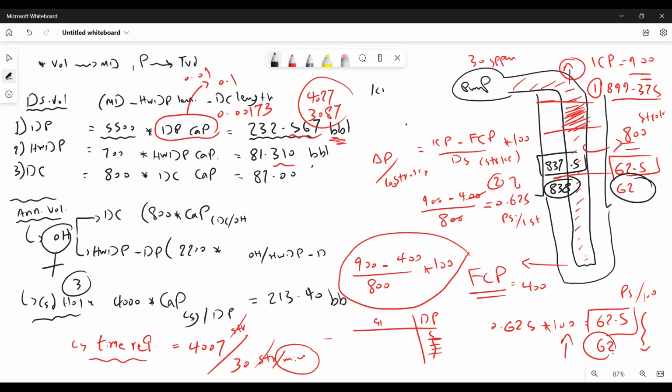For example, if you calculate kill mud weight and it is 15.1, good, we can take it like that, no problem, if it's only one decimal. But if it is, for example, 15.101 or 15.1001, we need to round up, so it will be 15.2. Okay, thank you.